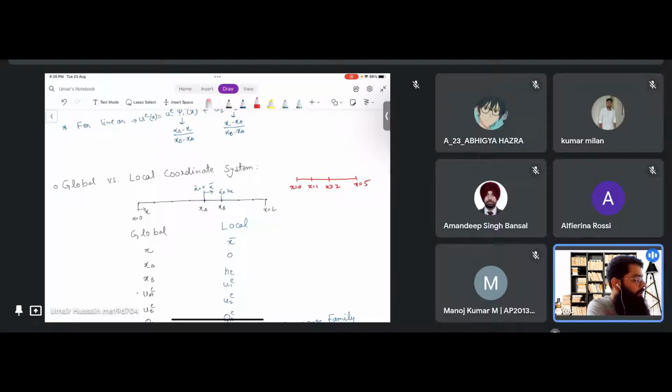This is defined on a global scale, with all coordinates in an absolute sense. But there's another coordinate system we are concerned with, the elemental or local coordinate system. Here we pick out one element and define things for that. We take another variable, x equals 0 here, x equals say the element length.